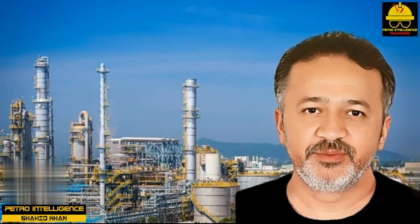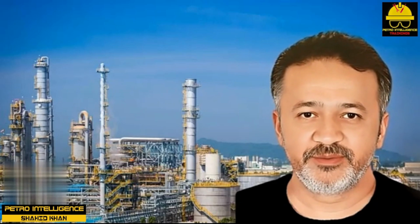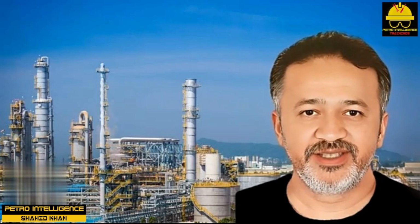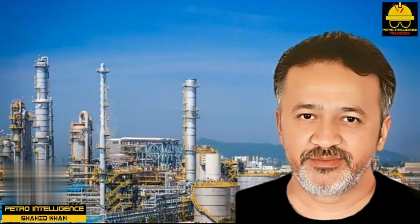Today we will discuss dumping or weeping through tray decks inside the fractionation tower. A distillation tray works efficiently when the vapor and liquid come into intimate contact on the tray deck. To this end, the liquid should flow evenly across the tray deck. The vapor should bubble up evenly through the perforations on the tray deck. The purpose of the outlet weir is to accomplish both these objectives as follows.